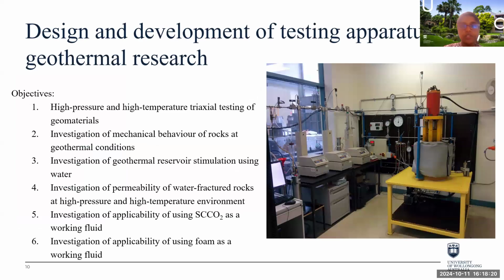This is a unique solution developed at 3G Deep Laboratory for geomechanics testing for high pressure and high temperature environments. So we extensively utilize this system to understand the mechanical behavior of rocks, hydraulic fracturing using water, as well as other different fluids like CO2, foam, and to understand flow behavior of rocks.